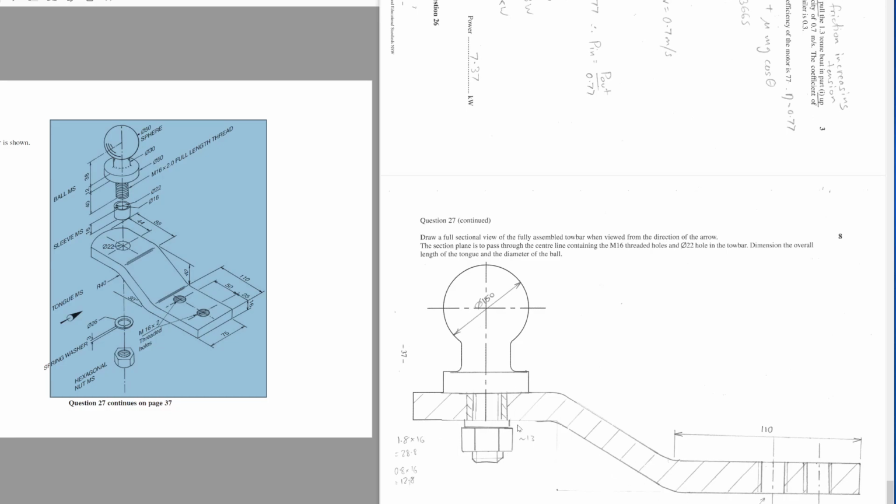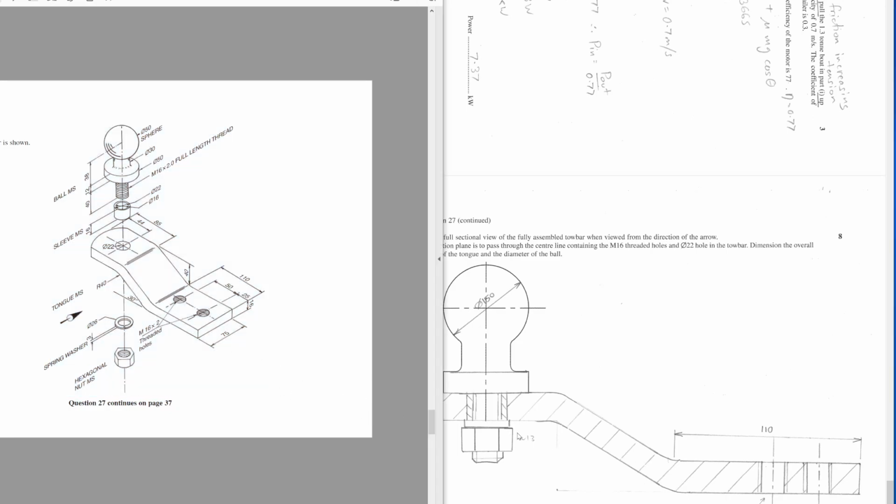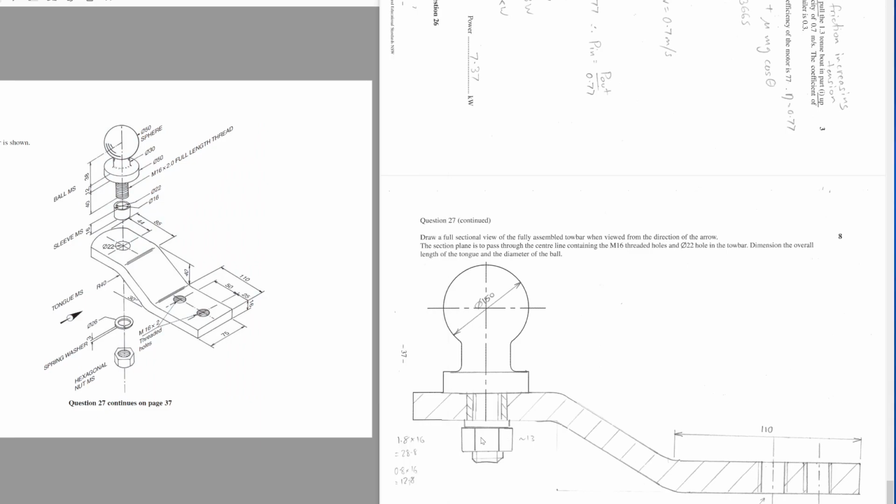Then I have drawn the washer. The washer dimensions were given in this case. And I didn't draw the spring. Yeah, so shoot me. Now this is a nut. So remember, head at 7, nut at 8. So this rectangle is going to be 1.8 times, but I wrote 1.8 times 16 and not 1.8 times 18.